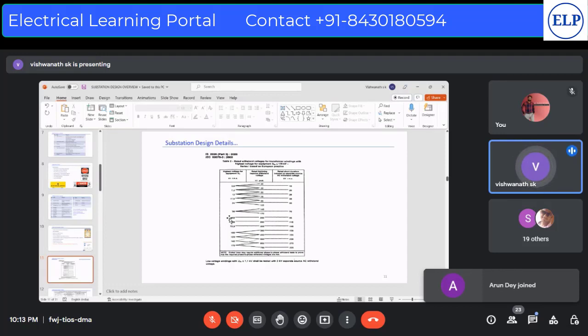This type test report is done one time by them. They will not conduct it in front of you. Only the power frequency test they will do. The impulse test they have already done at an approved laboratory.